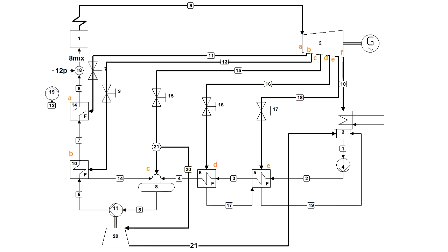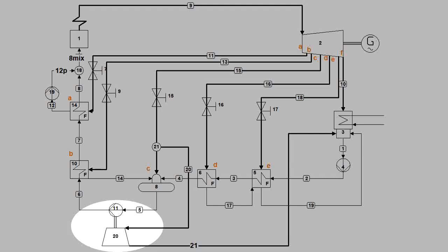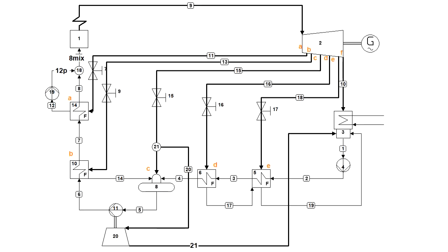And lastly, in this set of problems, we will illustrate or demonstrate implementation of a turbopump, which you can see here on the figure, which means that the main feeding pump doesn't have an electric motor, but we are actually using a small turbine, also operated from the main steam turbine bleed, which is mechanically connected by the shaft with the pump.